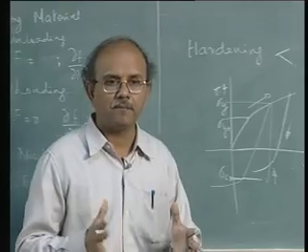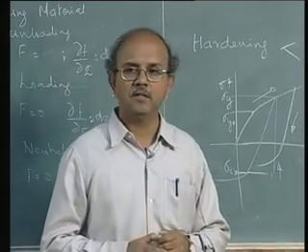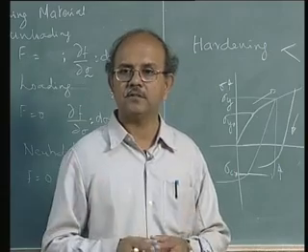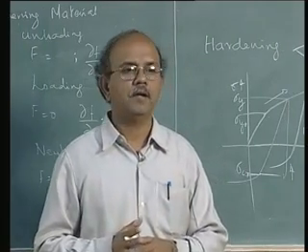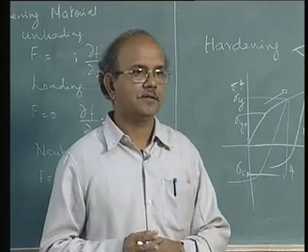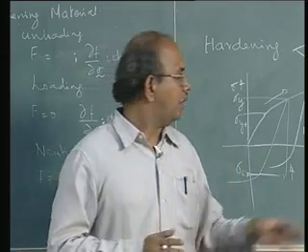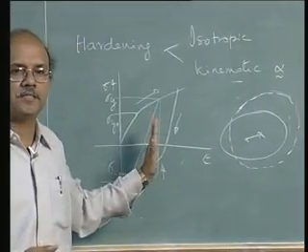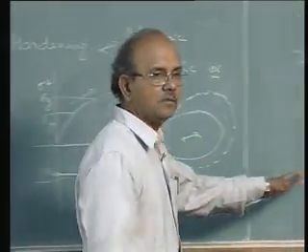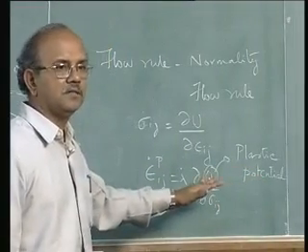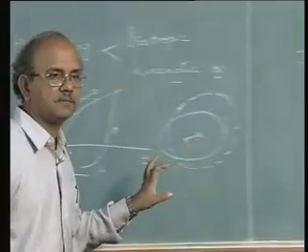So, that is why we developed the equivalent stress or the Mises stress, in order that we have a one parameter characterization of the whole of the stress state, and that can directly be compared with the yield strength of the material. Like that, now how do I express these combinations of epsilons which come about, which are very neatly written here, so that I can tie up this multi-axial case with a uniaxial case.